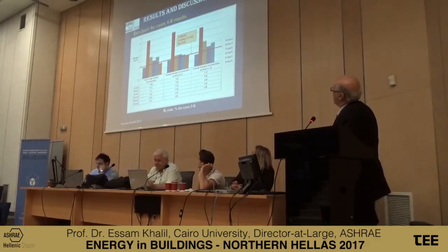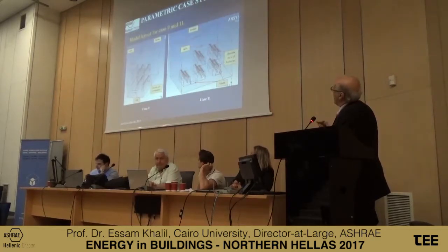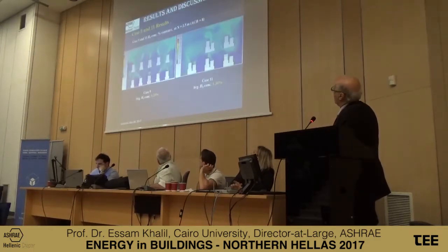And also comparison relative to the threshold of ASHRAE Guide 2020. Now if we have double stack, which means we have double rack of batteries, and we use this for compactness, what will happen here? We have case 11 and case 9, and this is the average concentration of H2O.